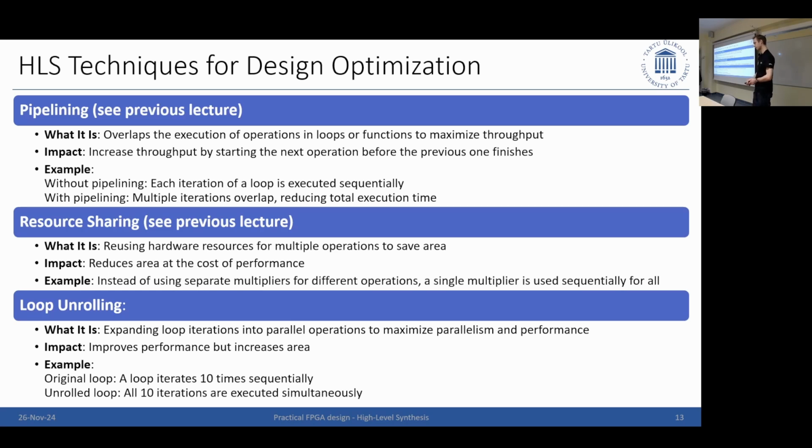Question: I'm not sure how likely it is to happen in FPGA, but sometimes loops are dependent on each other because some variable is building up. Will this recognize that? It should, yes. Sometimes loops can do that, but then there is already a dependency in the logic when you code it, right? Like you feed a value back in or something like this. This will of course be recognized because the logic path will feed back in.